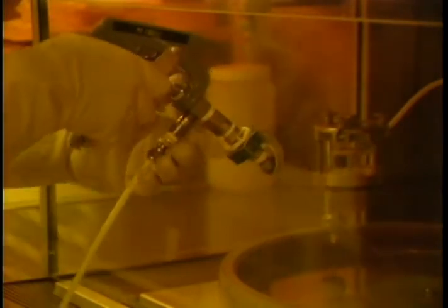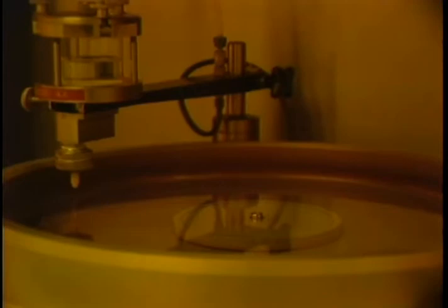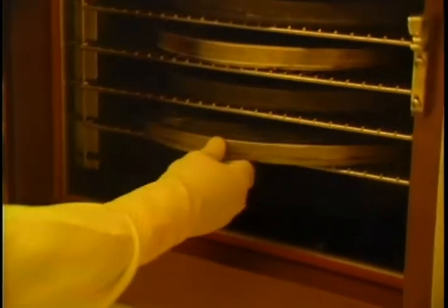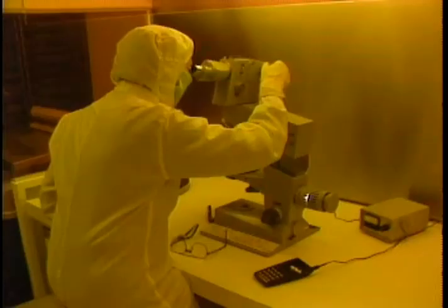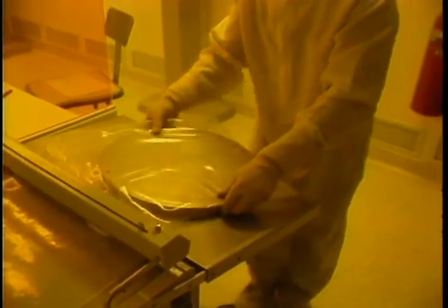Next, the glass is sprayed off again and coated with a positive photoresist. After the photoresist has been baked, several readings are taken of the emulsion thickness. A specially equipped microscope uses light to measure the laser-sensitive coating to see it meets specific standards. If it passes this quality check, it is stored until needed. When we are ready to do a recording, we put the customer's tape on the videotape recorder. We load the glass substrate onto the laser beam recorder in the clean room. And after that, the presettings on the command control desk, which is the setup for the master recording, are preset, and it's basically automatic after that.